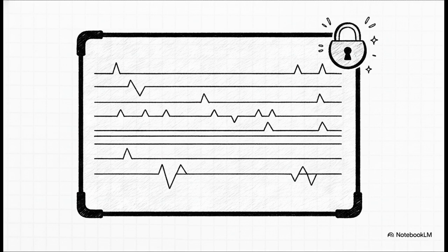Instantly, the wave window populates. If your Verilog code is spot on, you should see exactly these results. Your sum is 0100, your carryout is 1, and your overflow is 1. The software perfectly calculated that 1011 plus 1001 yields this specific result.